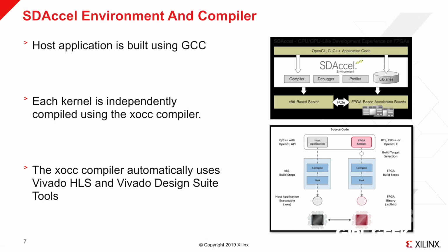The SDAccel environment provides multiple different tools to our customers. We have a debugger, profiler, libraries ranging all the way from low-level math libraries to high-performing DSP libraries. But the star of the show is the compiler. The compiler helps us provide a comprehensive solution for both the software parts and for the hardware parts. The compiler compiles the software part so that it can be run on the x86 machine, and it compiles all the individual hardware components, the kernels, so that they can go onto the FPGA. The kernels are compiled using the XOCC compiler, which internally leverages the Vivado HLS compiler and the Vivado design suite to generate bitstream for the parts that need to be accelerated.